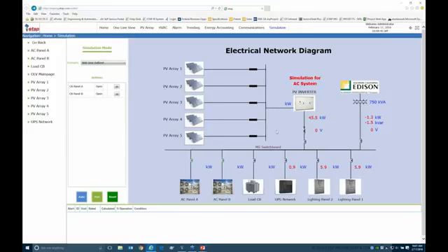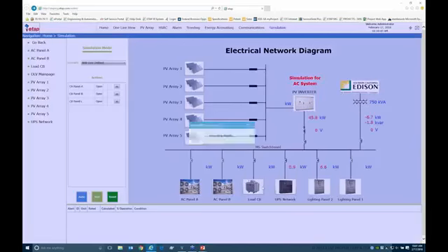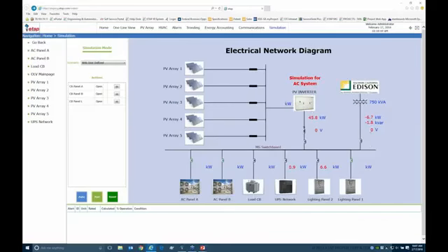And you can do this from anywhere, from within your network or outside your network, depending upon your security levels. And you can see that if you were to shut down those two air conditioners, yep, you would be actually selling about 1.5 kilowatts or so back into the grid. And as you cut more and more load into the system, we obviously expect more power to flow back into the grid. So this type of simulation allows you to even quickly come up with what-if scenarios, and these are essentially decision strategies you can make for a more complex system.